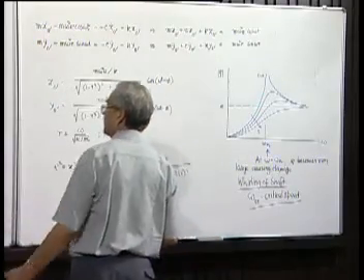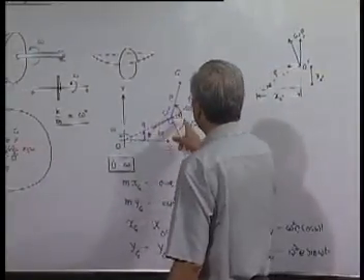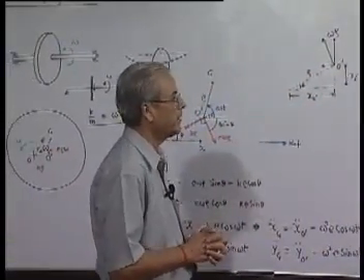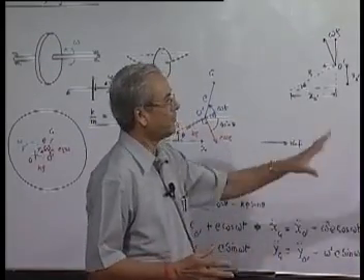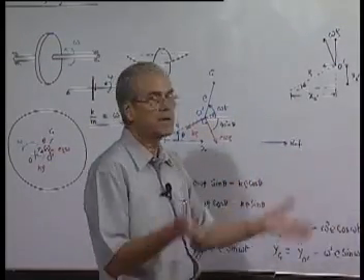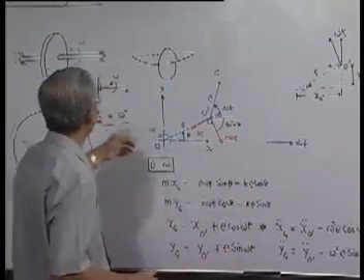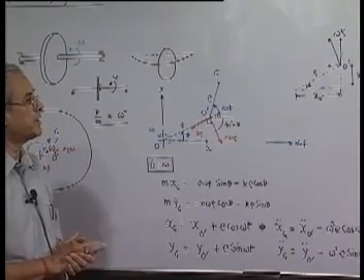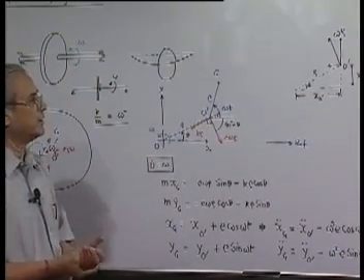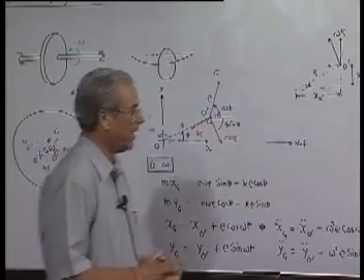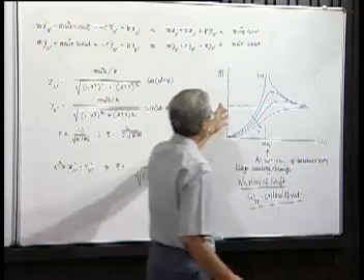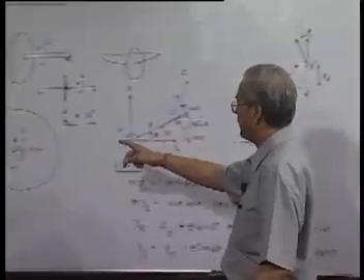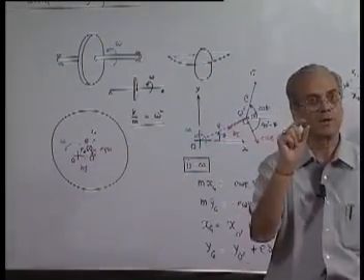Now, we have not gone into the details of finding the phase angle and all those things. It can be easily found out without any problem. But the main thing one has to keep in mind is that a shaft has certain speeds at which the system resonates, causing very large deformation of the shaft from its nominal straight position, and these speeds are called critical speeds, and the design should be such that they are avoided. At very large RPM, the deformation of the shaft will be the amount of error that was there while fabricating the system, that is, the eccentricity of the center of mass.